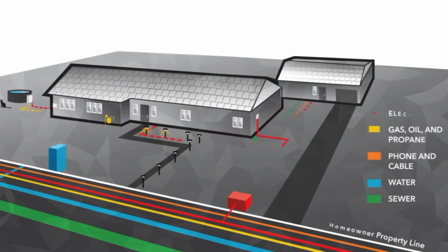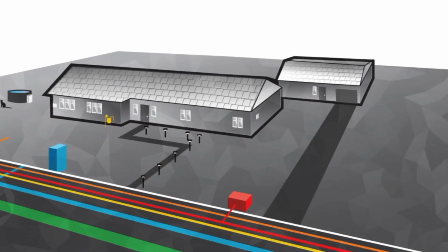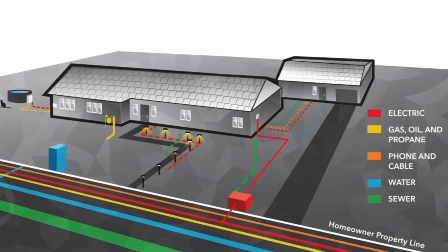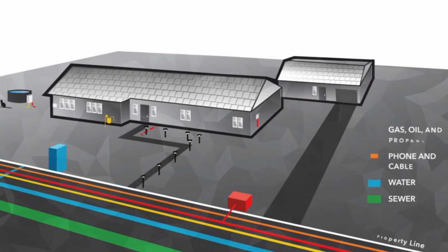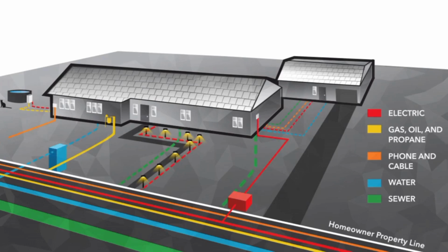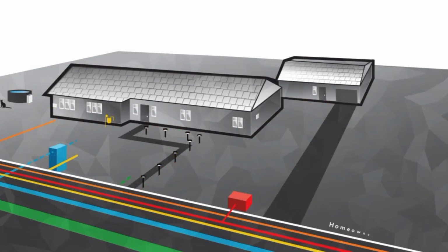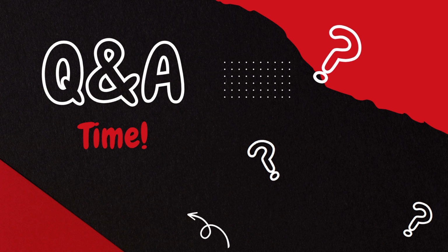And then the resistance, depending on what the material type is of the utility you're locating, is going to resist that current traveling down the line. So the best way to approach a locate is to think, how does electricity want to flow? It wants to flow to the path of least resistance. We want the electricity to flow to the mass. We want it to flow to the bigger lines, the bigger pipes. And so we start at the house, the opposite of how the product's getting to the house, we locate. Let it flow to where it wants to go, back to the main line.